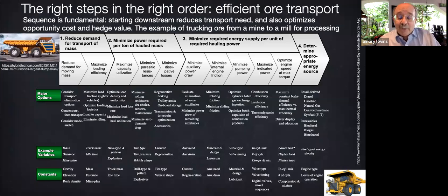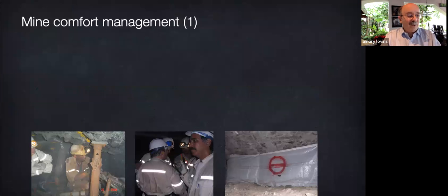All trucking problems merit this granular approach, and then you can electrify the mining trucks, like the 400-ton Komatsu at the lower right. That even gains net energy if the loaded haul is downhill, that is, the mine is above where you need to get the ore to. Or trucking itself could be designed out using newer innovations like Barrick's rail conveyor, a cross between a conveyor and a railway. Now, the highest modern mining ambition is to send only robots underground, not people.